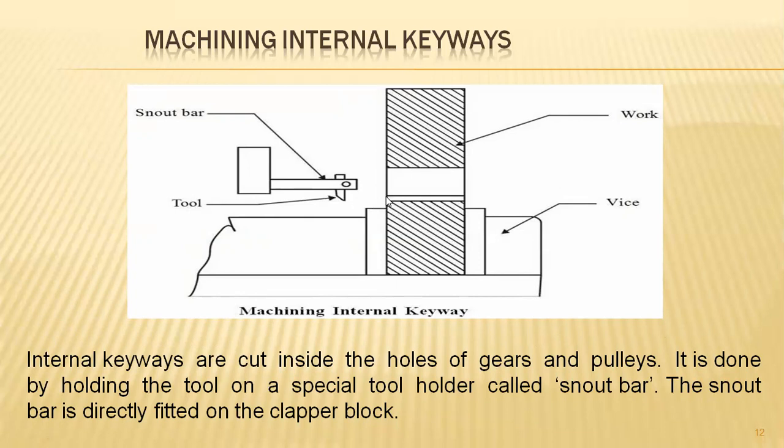Because if this has been marked up here, this is the material to be progressed in horizontal mode of working up to a depth of cut of 4 mm. Initially a 2 mm feed will be given and 2 mm will be removed, and the idle traverse will bring the tool back to the initial position again. And secondly, another 2 mm of material will be removed. So this is the frequent motion of this shaping machine, as we discussed, related to the slotting machine also.